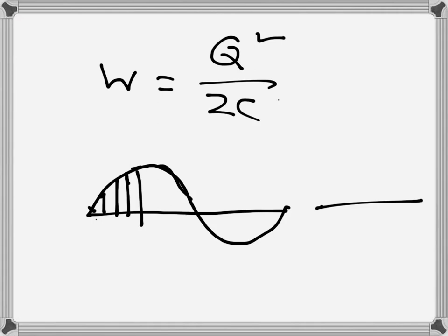So basically it's the same principle, but the way a capacitor acts in a circuit is, though the current origin is the same, for DC it acts as a current blocker, so it acts as an open circuit, while for AC it becomes a sort of short circuit. Not probably a short circuit, but it gives an impedance, which we don't want to talk about here, but basically it allows the current to flow. We can actually say how much it is; it's called reactance.